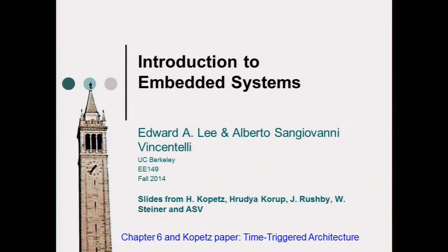We have seen that in electronic circuit design, the mechanism for implementing synchrony is the registers and the clock. Everything moves, the computation moves from left to right, so to speak, across combinational logic.